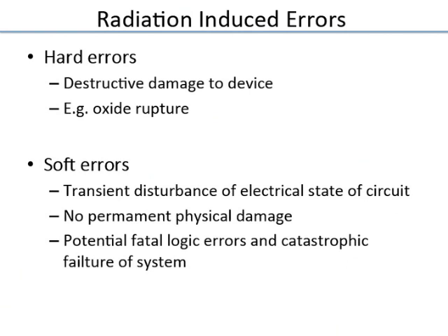Soft errors are errors where that kind of damage doesn't happen. Charge gets created and then it perturbs or changes the state of the circuit, because your circuit is essentially a sea of capacitors which are charging and discharging. But this error can be pretty fatal and catastrophic. Your whole system can mess up.